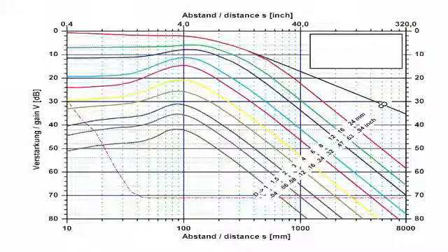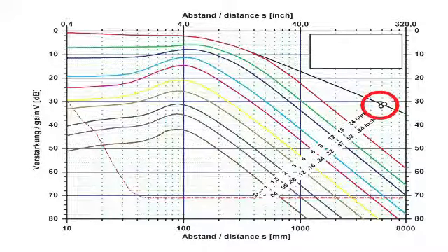Within the DGS diagram, the distance dependency of the echo amplitudes from large reflectors, in this case the back wall, and small reflectors, flat bottom holes having different diameters, is shown graphically. When using the DGS method, the term equivalent reflector size, or ERS, is used when referring to the diameters of flat bottom holes.